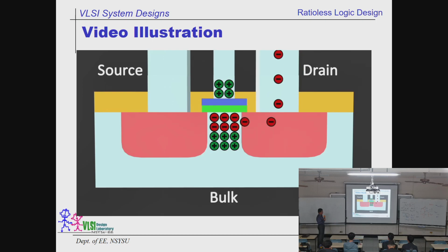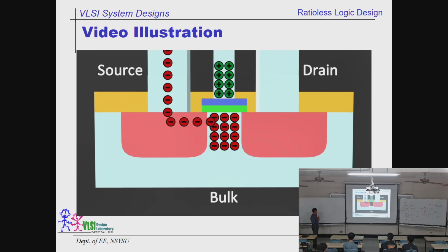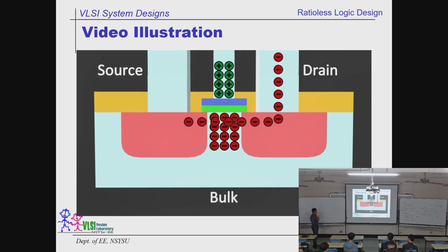It should be noted that the current between source and drain can be increased through raising the voltage potential, which leads to a stronger electrical field and thereby a larger n-channel. Since no current is able to flow between source and drain when there is no potential on the gate, this type of transistor is called enhancement mode MOSFET.